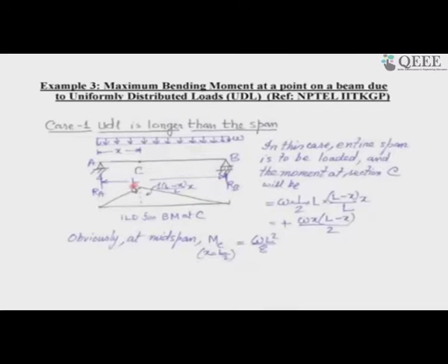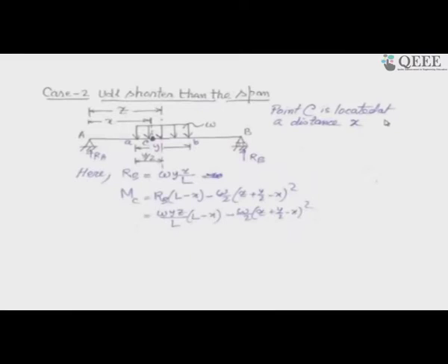I have an extremely simple exercise of finding out the area of the influence line diagram multiplied by the UDL, which gives me the bending moment from the influence line diagram. This is an influence line diagram, not the bending moment diagram. So that gives the influence at that point of the bending moment caused by the UDL at that section. Like that, if I am at the midspan, I will find from this formula omega L square by 8, and that will convince us that I am on the right track. Okay, now let us go to the next.